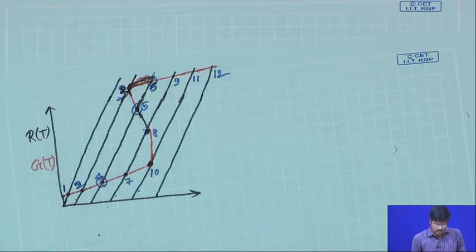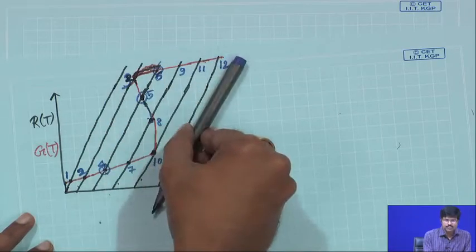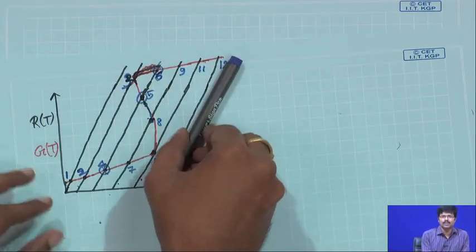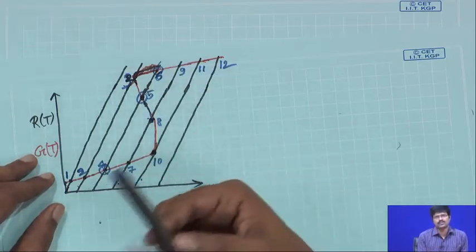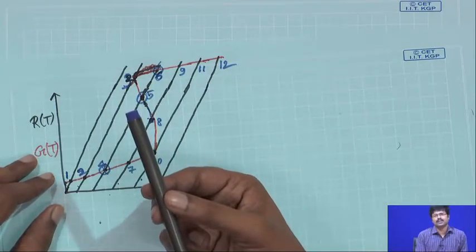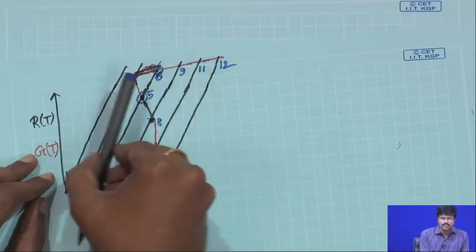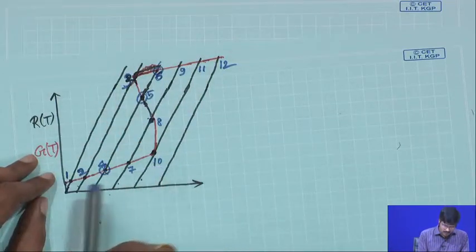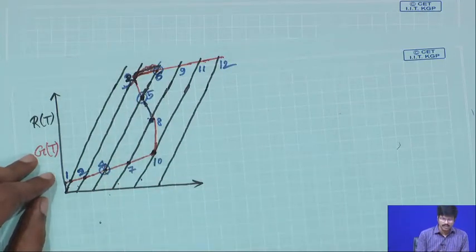Okay. So, you see that depending on where this RT line is, which is determined by the values of Tc, the coolant or heat transfer fluid temperature, and T0, the temperature of your inlet, your line will change, and then either you may get only one steady state, you might also get 2 steady states, or you might get 3 steady states. Typically you will not get more than 3 steady states.